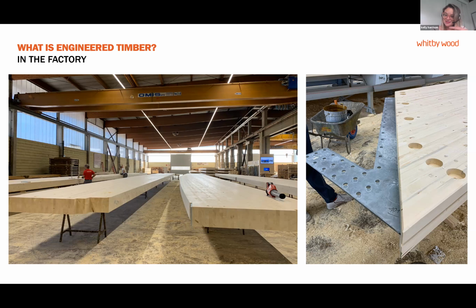how is it going to be loaded in the lorry, how is it then going to be held up and fixed on site? All of those things have caught me out in the past, and we've had issues with something along the way, and we've had to retrofit something at the end. And so really understanding those details before fabrication, during the design process, getting it costed correctly is super important. So yeah, it's just an example there of all the holes and the bolt holes and the screw holes that have to be pre-drilled will be done in the factory as well. So you really have to understand all of that beforehand.